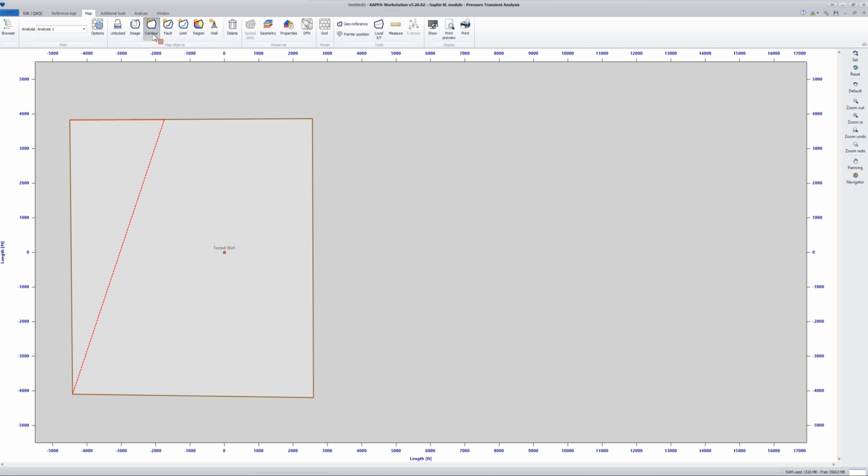Okay, and back to click again to the contour to confirm that you are satisfied with this dimension. Okay, the second thing that I want to do is to make a scaling, to transfer the actual scale to my map.